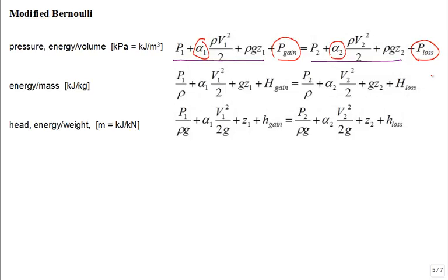All right, so for flow in a pipe or a duct, some sort of enclosure where the fluid is flowing, we have alpha, the kinetic energy correction factor. In almost all cases, alpha is 1. But if you want to be a purist and really detailed, you can calculate alpha. And the alpha equation was something like 1 over area, integral across the area of V divided by V average, cubed. True?